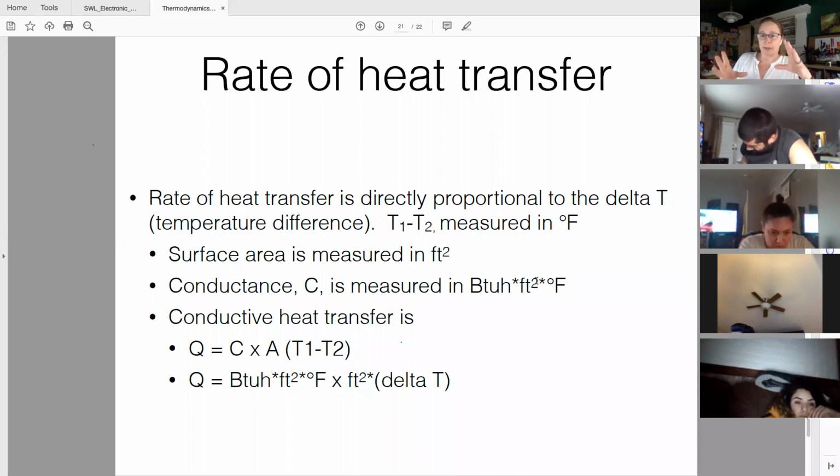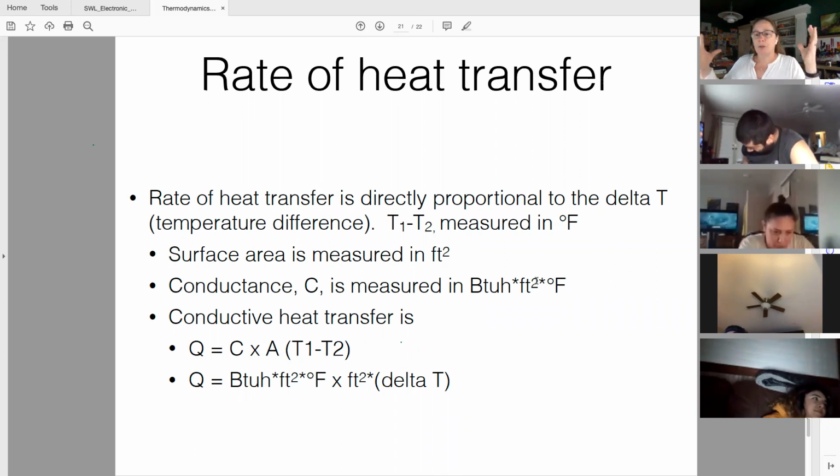It all comes together in the psychrometric chart, and you can look up where all those different values fall. Certain ones are in the thermal comfort zone, and a lot are outside of it. So when you get into space conditioning, it's all about treating the space around you to get the temperature and the humidity into that thermal comfort zone.